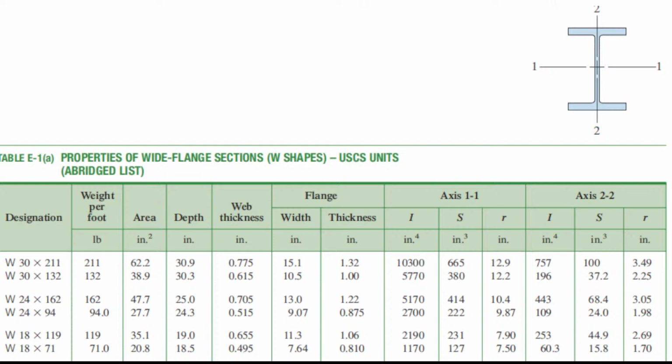If you consider the connection, there is what we call the K factor, and the K factor is equal to 1 if the column has a pin connection. Assume that this steel has a proportional limit of 36 ksi, so the A36 material. Then repeat part A, where the length is changed.